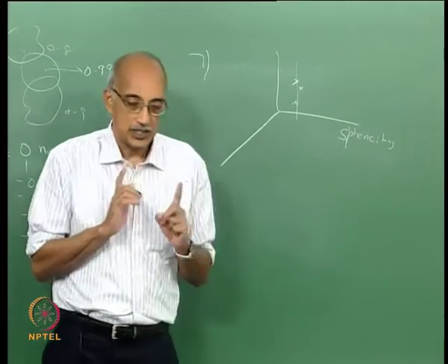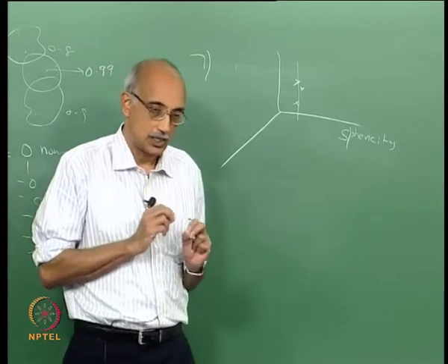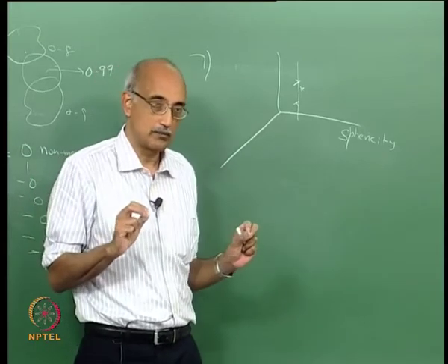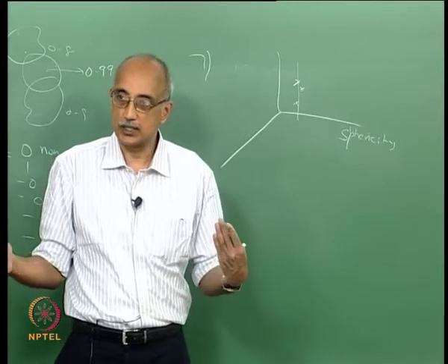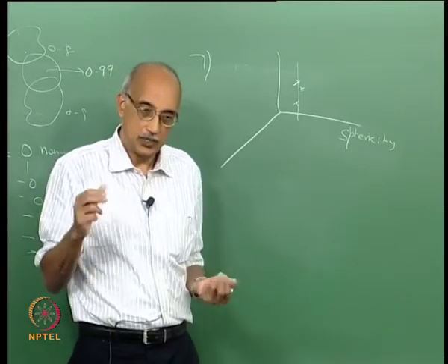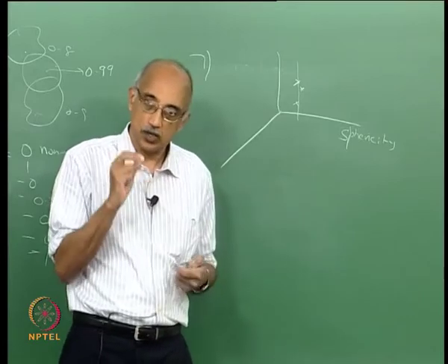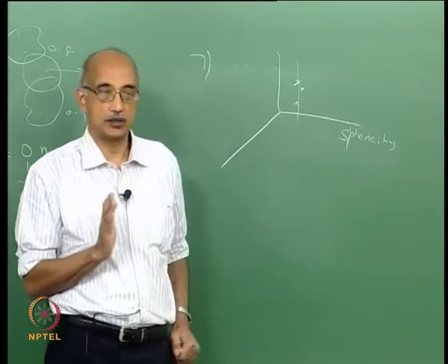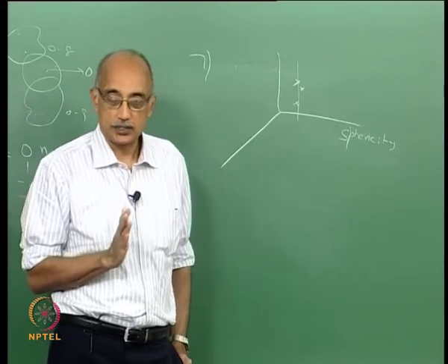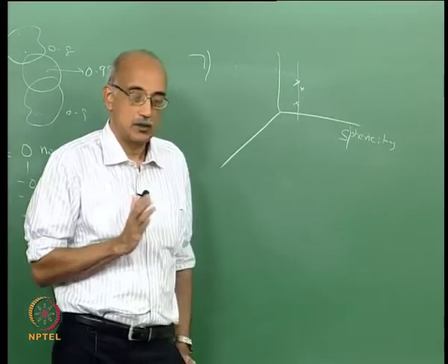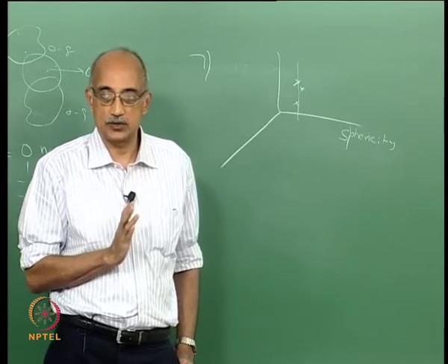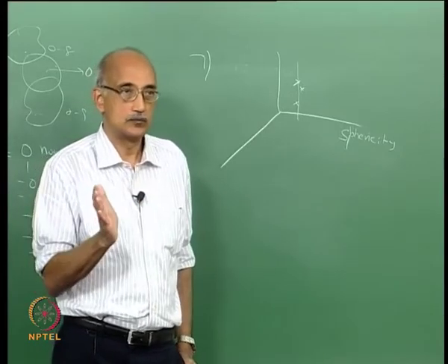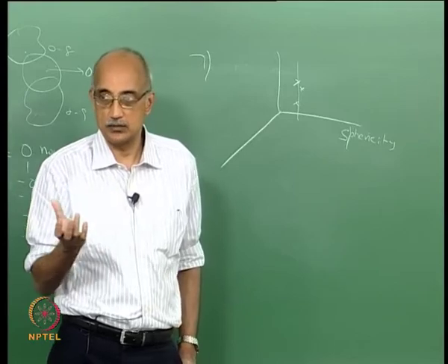So, the key difference again is the common property approach says do not worry too much about mathematically minimizing the deviation of the reference object from your object, but instead be even more decisive on what are the critical shape characteristics for your process and try to home in on a shape that gives you an exact match in terms of these characteristics, even though the net deviation may be greater.